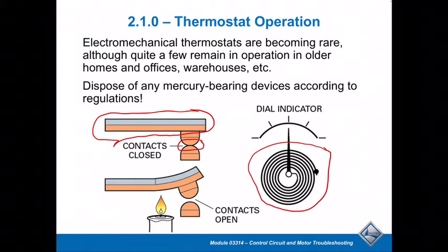And I'd also mention these millivolt thermostats, like the 750 self-generating thermostats. One of the interesting things about those is that in many of the fireplaces that you might see used in the industry, they would have a self-generating thermostat that would control the gas valve primarily. They didn't really pull in relays or anything like that.